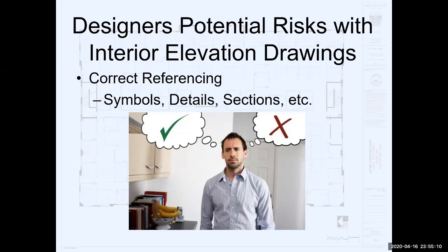The detail references become important because we're going to lead the viewer or the person reading these drawings to even more detailed information elsewhere, so that detail symbol becomes important. How we illustrate a section cut at these walls, especially with cabinetry, is likewise important for folks to understand what's going on with the cabinetry.